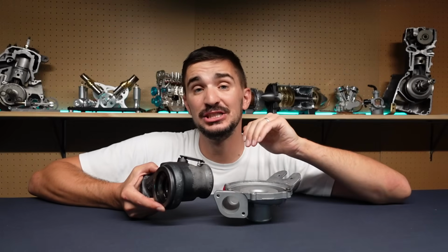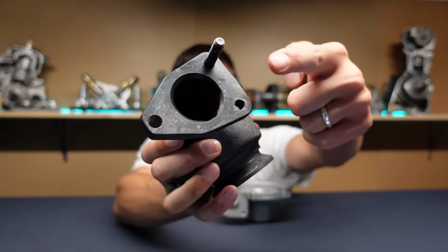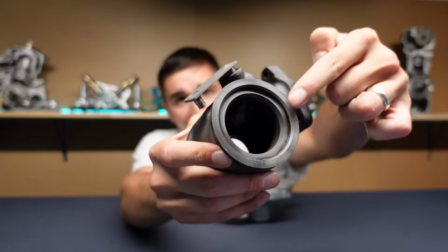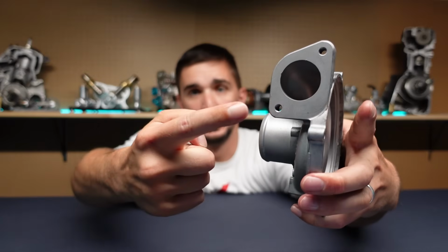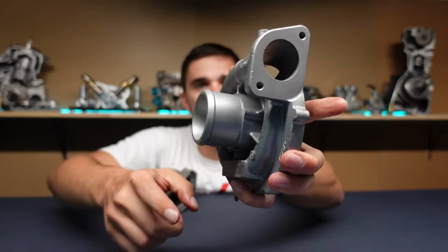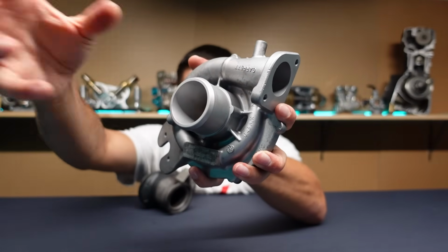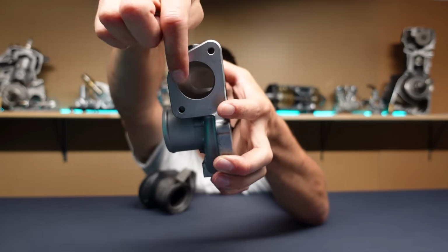Now the turbocharger needs to be connected to the engine at the exhaust manifold. So that's the turbo inlet, which goes to the exhaust manifold. That's the turbo outlet, which goes to the downpipe. And here we have the turbo intake side outlet. This goes to the intake manifold of the engine, and here we have the turbo inlet. The air filter piping from the air filter goes here. This is where the air comes in, and here the air comes out.